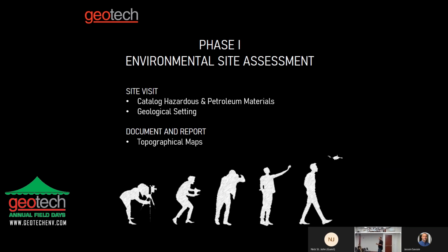And so let me go back a little bit. We fly an aircraft and it's taking individual photos of an area. And then it loops around and takes individual photos of the next line, kind of like a lawnmower pattern. We're using an overlap of 70% forward and back and usually 70% side to side, because we want to get as many pixels of any given section as we possibly can. 7 to 9 images of any given section is our goal to make sure that we have really good coverage. And then we take those images and stitch them all together.